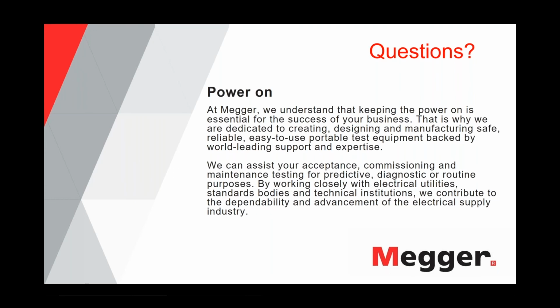All right. Robert, is tan delta a worthwhile test for EPR cable? Does EPR cable fail by water treeing? So the answer is yes and yes.